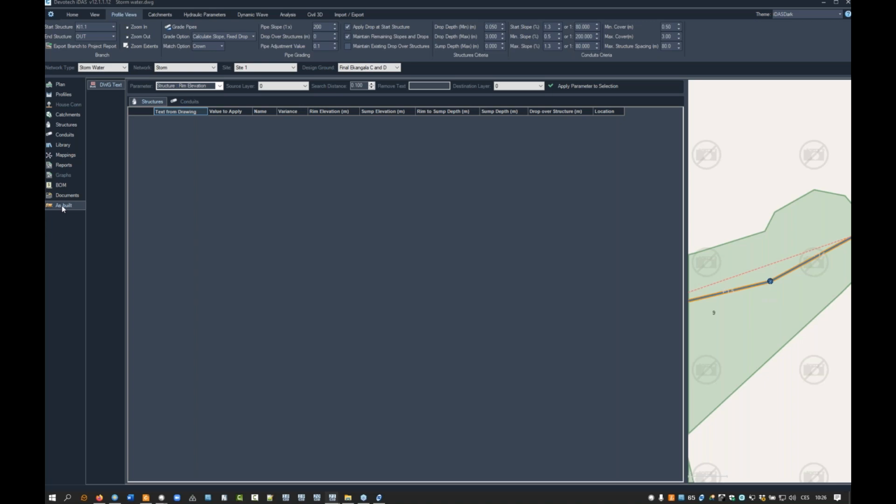And what it does is that you can assign the elevations or the properties, all these properties, like a structure rim elevation, sump elevation, or pipe inverts, crowns and so on, from the text in a CAD drawing. So if you get the drawing from the surveyor with the polylines for the pipe network, but those polylines are often at a 0 level, it will give you the text for each invert level at each structure. To recreate that network is very tedious to do manually, because you need to check what's the elevation, go to pipe properties, assign it. This tool can assign it automatically from the text.